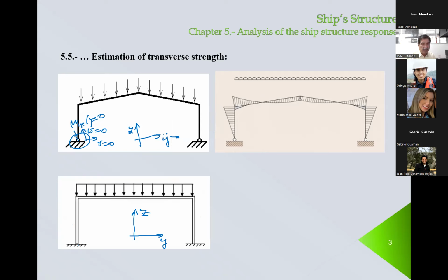So if we start here, the deflection will be like this, and you go in this direction. But here, there is no slope. So in this case, if this leg tries to rotate in this direction, the bending effect generated by the foundation prevents that and generates a moment and brings it back.